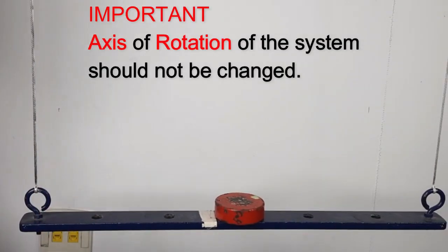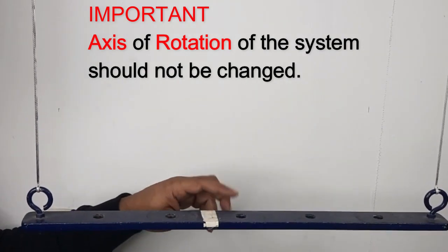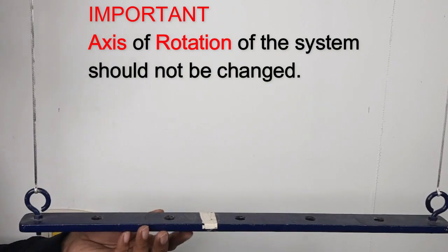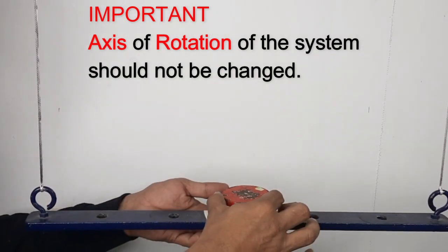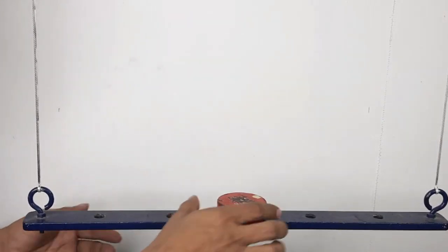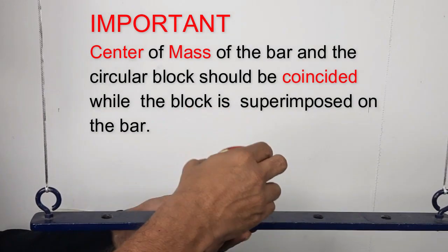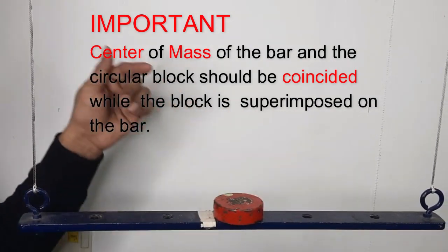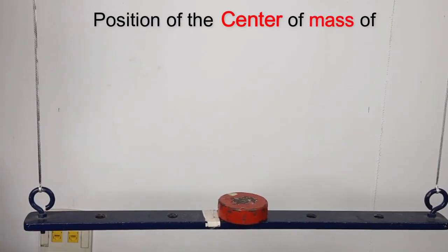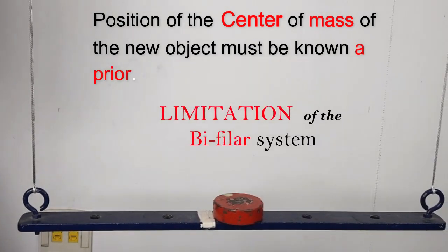Here you must remember that the axis of rotation of the parent system, which you have already calculated, and the axis of rotation when you have put the auxiliary system should not change. That means the center of mass of the unknown system should coincide with the center of mass of your parent body, and for that it should be known a priori. This is the limitation of bifilar suspension.